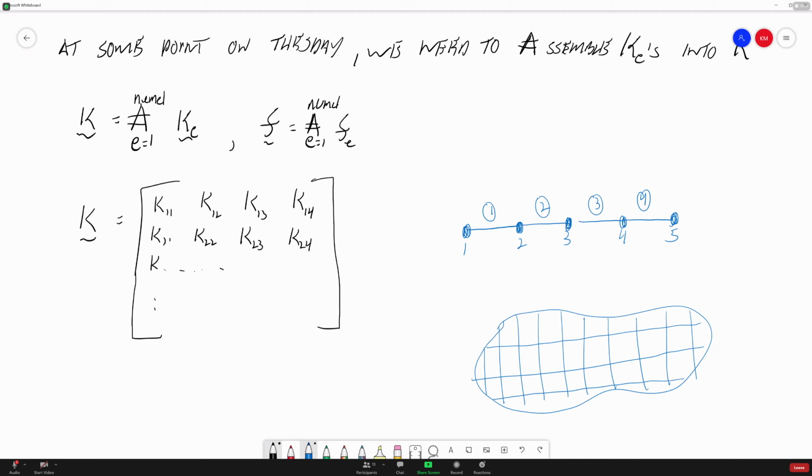That's a whole other routine and sub-application that's going on in a finite element code. We're talking about when you already have this, how do you make sure that the results that we're going to get out of our finite element code are reasonable? And that's what it's checking for. Are there discontinuities in here? Like you said, maybe you have some way that you have an element that has a negative volume or no volume or whatever there may be to it.